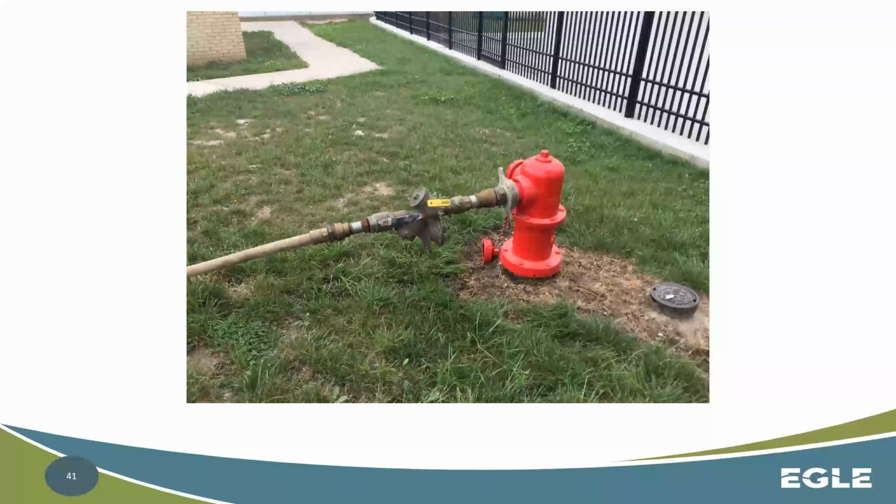This here is a setup to actually have backflow prevention occur. This is very good, right? You've got a dual check here with a pressure relief. So this is actually a PRV. This is a great scenario for stopping a backflow event from happening and contaminating the water supply.